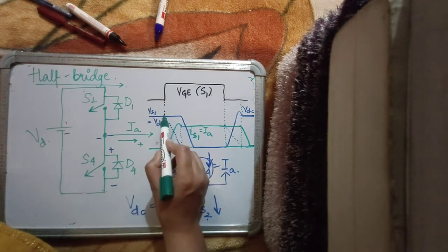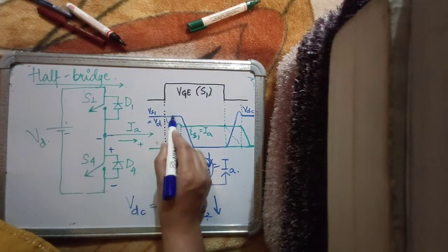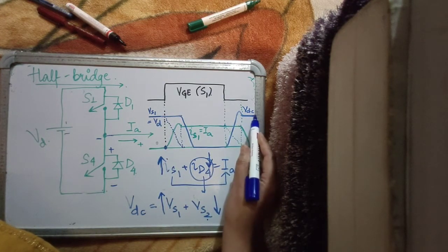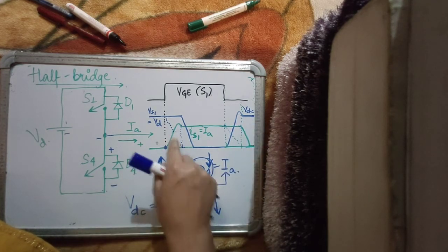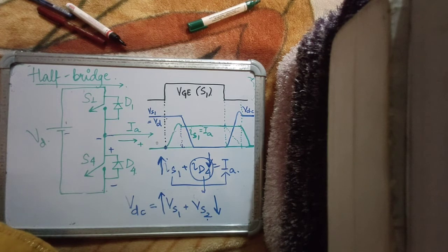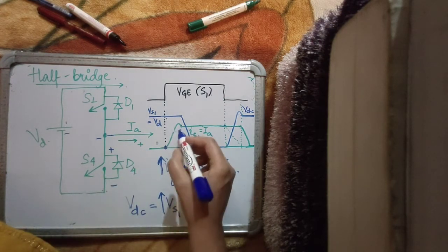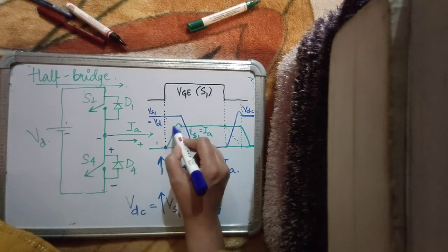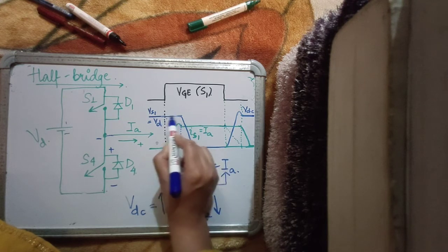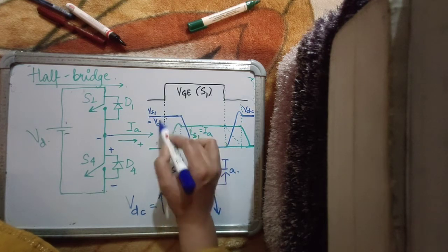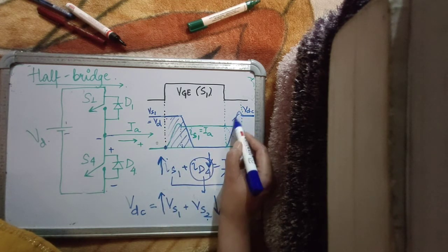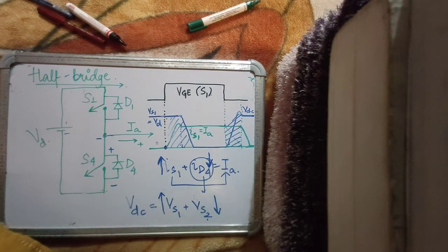But because voltage stays for some time while the current increases, and the current stays for some time while the voltage increases during turn off, you see that in diode clamped power electronic circuits there are actually more losses, right? Earlier in this interval there used to be switching, with voltage rising and current falling, but here voltage is constant and high, so obviously there is more area under the curve as compared to what we had calculated. So there are more losses in practical power electronic circuits.